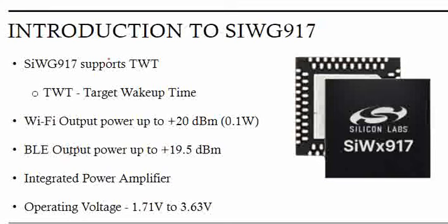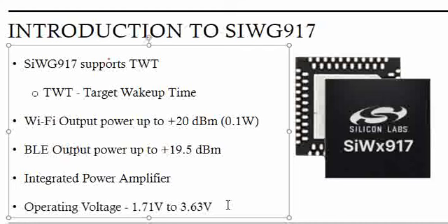And one important and very typical rating that we see with chipsets, especially MCUs, is generally a range of 1.8 to 3.6 V. This particular SiWx917 SoC has typical ratings that are actually something interesting, with a lower side of 1.71 and a higher side of 3.63.